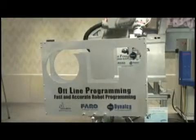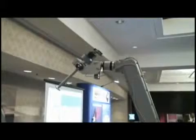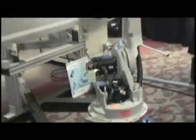The reason that manual teaching has to happen is that robots by themselves are not very accurate. A standard robot will be off in its accuracy anywhere between 5 to 10 millimeters. And then there's the error between the robot base and the base of the fixture, as well as the location of the tool center point, which is also called TCP.